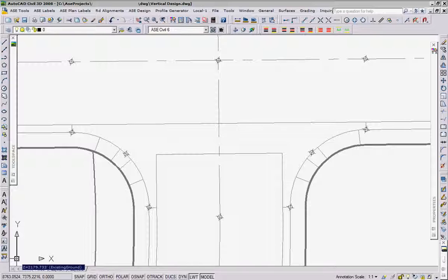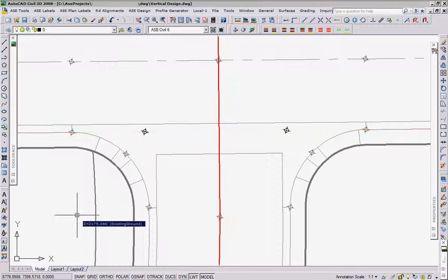The design markers are a design tool that you can use in any way you'd like. The degree of control that you want over your roadway design is entirely up to you. For example, on the alignment component shown here, the designer may want to set additional design markers at the intersections of the backs of curbs of the two intersecting alignments within the valley gutter. Then for the intersecting alignment centerline, the designer may place design markers on the valley gutter where the centerline crosses.